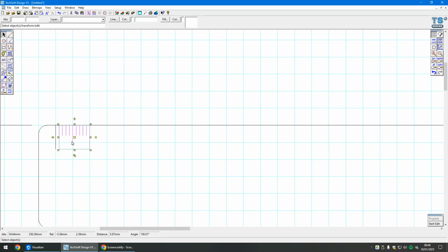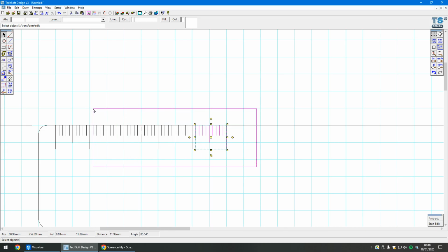Okay, now I could copy and paste that, and I could then continue to place these in position. And just notice here when I pasted that, I've got step lock turned on, so it's snapping with this 1 millimeter grid layout. If I put that to grid lock and I paste it, notice now that it just snaps straight onto the grid, and I can now just place all those in. So that's one way I could do it. But I'm going to show you another way as well.